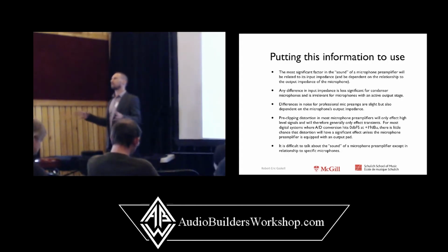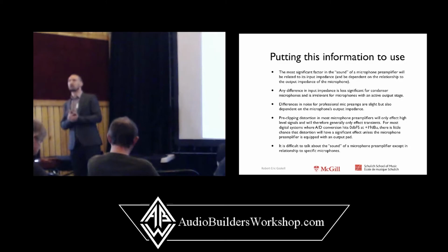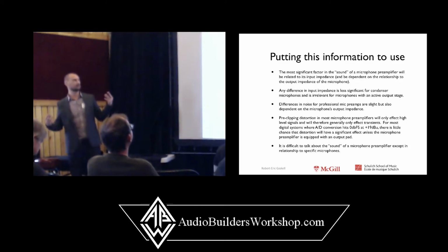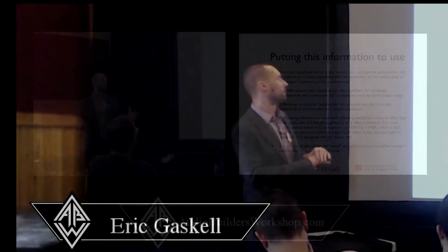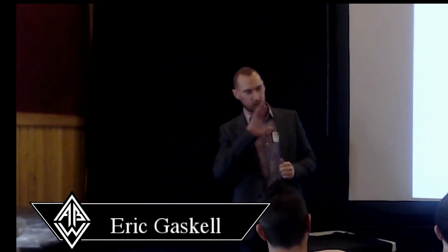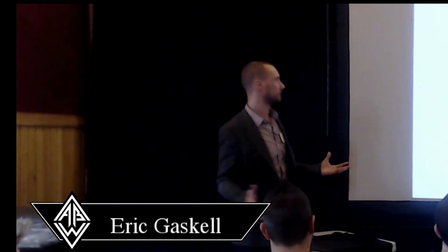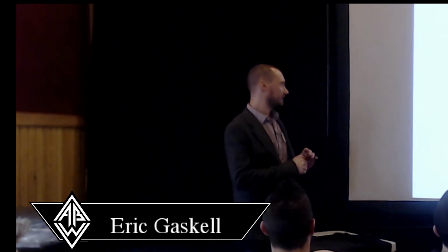All right, so just to kind of recap everything, I think I'm probably running out of time anyways. I still believe that the most significant factor in the sound of these mic pres is going to be the potential alterations of the frequency response, whether it be because of the interaction between the output impedance of the mic and the input impedance of the microphone preamplifier, or the intentional roll-off of high frequency and low frequencies by the designer, or unintentional side effect of the gain bandwidth characteristic of the amplifier. Changes in frequency responses are going to really contribute to perceived differences between mic pres.